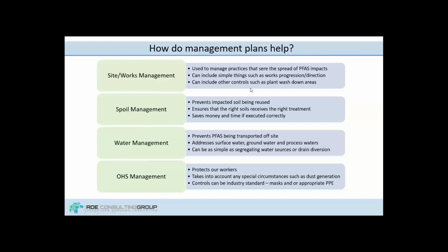This can manage the spread of PFAS, and these can be as simple as having practices in place for how we treat water and use water on site, wheel washes, segregation of stockpiles, or the order that we work, working from less contaminated areas to more contaminated areas of the site, or taking into account aquitards. So there's a number of things that we can do that reduce the risk of the actual physical works or how we operate on a site.